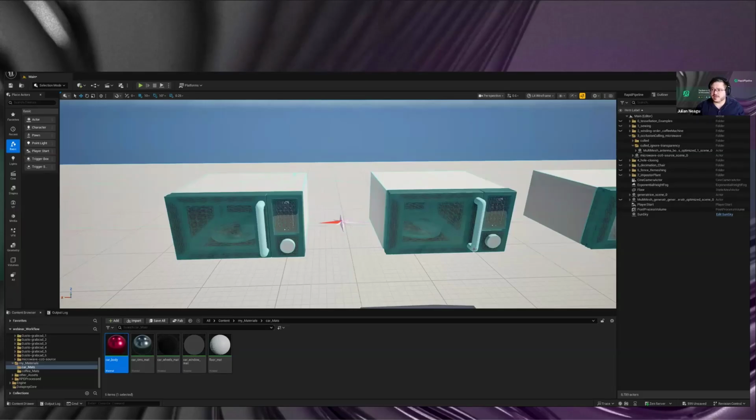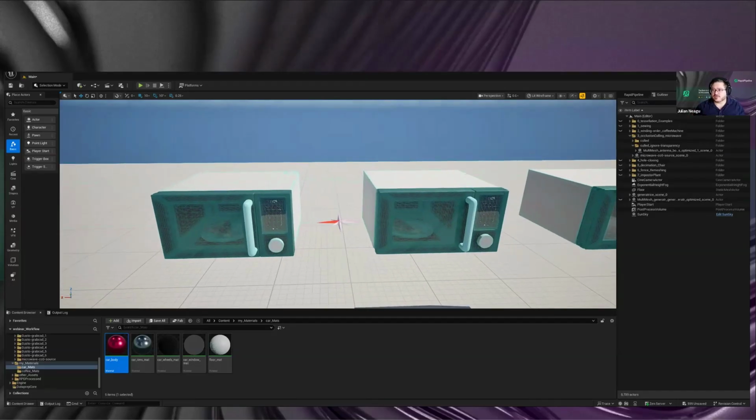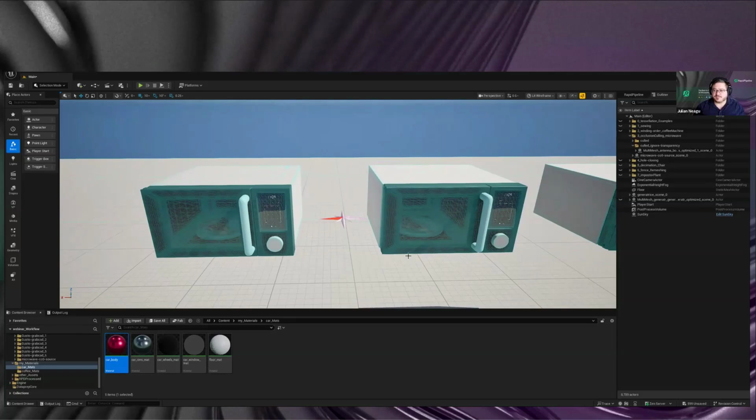If you have certain parts with really high resolution details and then very low resolution faces and larger surfaces, that in almost all cases didn't work very well, and more traditional LODs, either created with Unreal or with our decimation tools, work way better than Nanite in terms of visual quality. But this is just as an FYI: we deactivate it at the moment on the static meshes when importing. We're happy to revisit that and see if we can have it interact with Nanite in a way that doesn't produce suboptimal results.